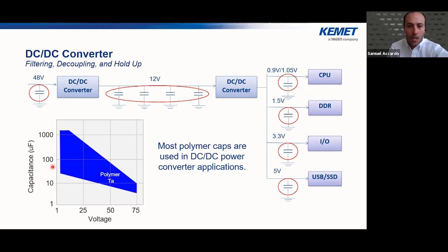And what you see on the bottom left-hand side is a range of where the capacitor falls for capacitance values over voltage. And then I guess one of the final things I wanted to say is based off of decoupling. On the previous slide, I mentioned how there's a very quick capacitance roll-off frequency approaching a megahertz. So typically, these parts are used in conjunction with other technologies, in particular ceramics for decoupling applications, because if you have a target impedance and a target frequency, you want to be sure that you're using a wide range of different types of devices that are going to push down those impedances at certain frequencies based off of the application. So the tantalum capacitor does very well at frequencies lower than a megahertz for decoupling applications.